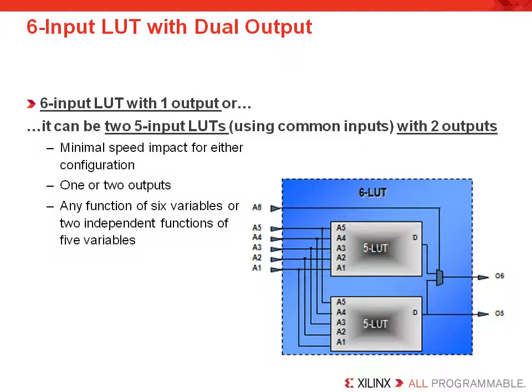Every customer must understand the input limiting nature of LUTs. Because many customers are used to building with ASICs, it is important to understand that the HDL code you write needs to be optimal. This is because ASICs are faster than FPGAs, and it's much easier to get good speed from an ASIC with suboptimal code. This is highlighted when you consider what you would get if your combinatorial logic had 7 inputs. Because the LUT has 6, your synthesis tool would be required to add a second LUT in series with the first. This would then dramatically increase the delay associated with this path and cut the maximum frequency possible.